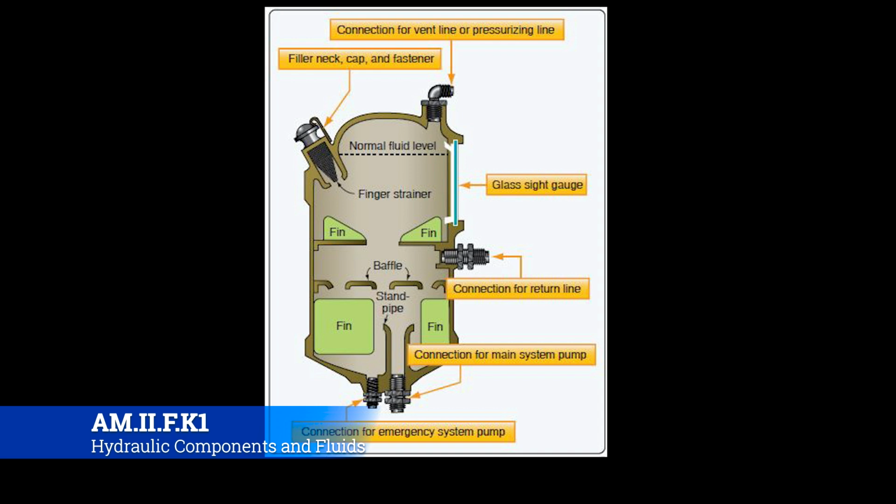Then there's always going to be some way to know how much fluid is in there, and it's usually going to be a sight glass, like on this one, you can see on the right hand side. These can look in a variety of different ways. They can be a long graded sight glass, like you'd see on our IDG on the JT9s. They have a long, rectangular sight glass that says, here's a gallon, here's 2 gallons, here's 3 gallons, or whatever the unit of measure is.